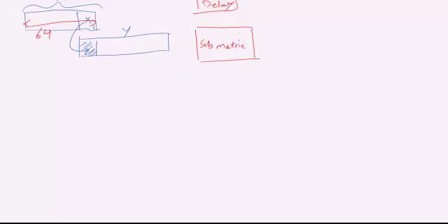The role of the Submatrix block is to copy part of a sequence. It gets a sequence at the input and gives you part of that sequence. You have to go to Simulink help to find out how to configure this block so that when you give X as the input, X1 is the output.